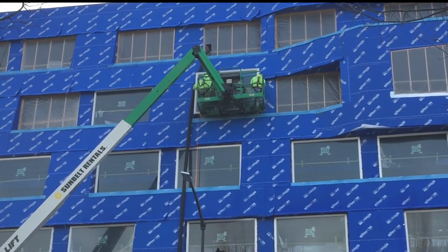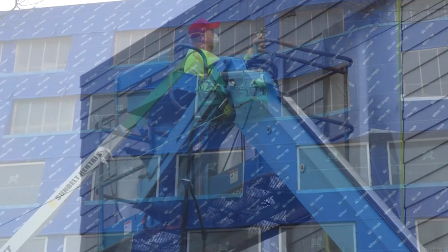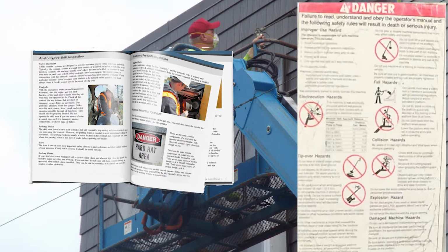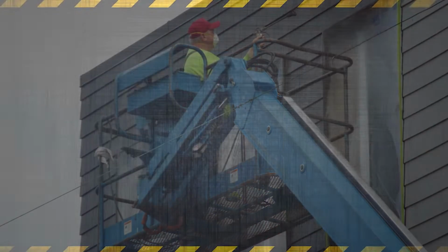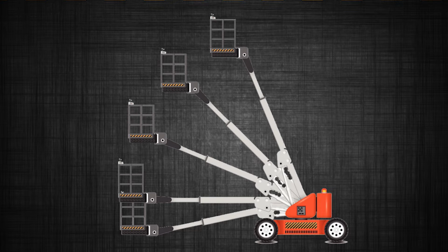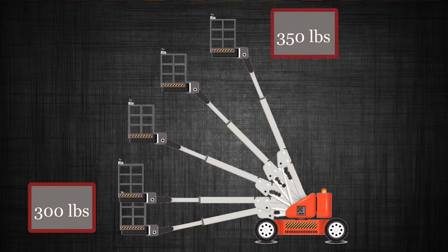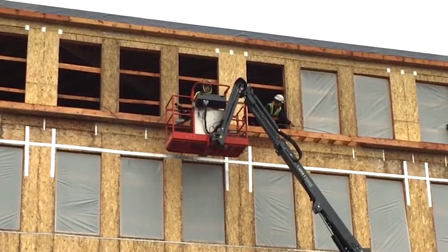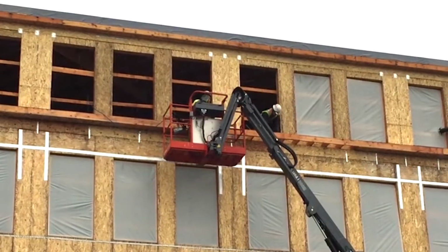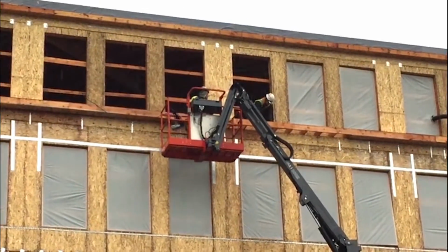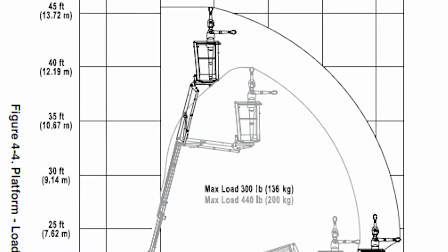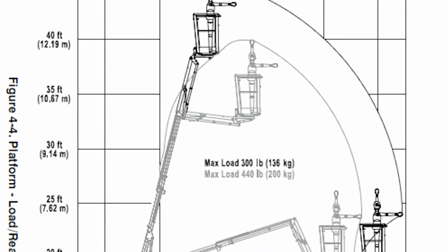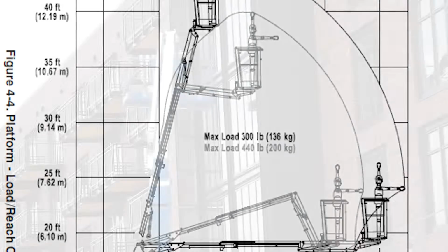Each aerial lift has a maximum lift capacity. This can be found in the operator's manual and on the data plate. The lift capacity can vary, depending on the position of the boom. An extensible boom lift, with the boom fully extended and lowered, may have a lower capacity than one that is straight up and down. Most lifts have one maximum capacity listed. If you keep the load on the platform lower than this maximum load, you will stay within the capacity limit in all boom positions. It is critically important that you know the maximum lift capacity of the aerial device. Your life depends on it.